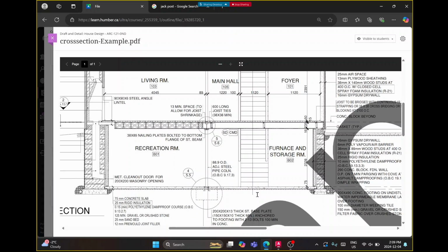So I believe they're showing this dashed line down here. That's an extra bit of footing, or a piece of concrete poured as a base for this column. So in their floor plan, we haven't seen this because they don't give us a basement plan. So all this may seem very unusual if you haven't seen this in the drawings before. But what you can kind of deduce from this is that they have a line of columns in the basement. And in every column they have something called a pad footing, which is a big block of poured concrete. And so these bolts that we show actually sit inside of that concrete.